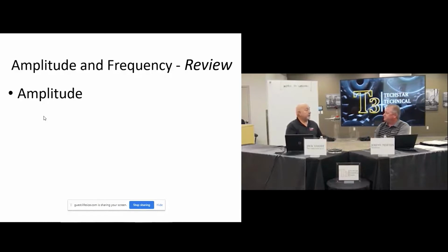Yeah, just a couple of weeks ago, I was at a location that was monitoring in the axial position on a gearbox. It was right in the middle of the gearbox, and the vibration was high because it was giving the stereo effect, and there was no support there. If you went off to the corners, you had normal vibration, but there it was amplified by 3 times. Yeah, you're getting that flex of the gearbox casing instead of directly over where the bearings were, and more rigid. The gearbox had proximity probes on it monitoring the shaft, and there were no issues. Zero problems. They were all concerned about that one point right there, and I was like, don't measure there. So installation is key on these systems.